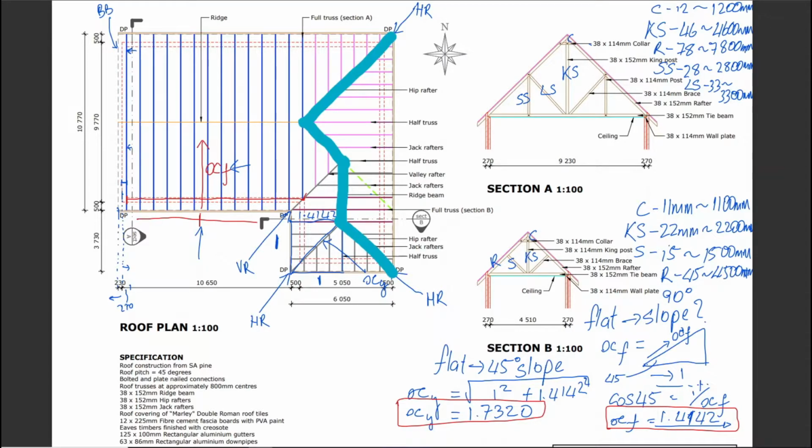So what we're saying is you're going to take 10650, because it doesn't include the 230. 10650 starts here. You've got to subtract 270, and now you've come to this face here, and whatever's left of that 10650 means it comes all the way here. You're going to add 500. Now you're on the outer face, which means you're somewhere down here. That's how far you've measured. You're going to take whatever is left on this side. So I say take 5050.